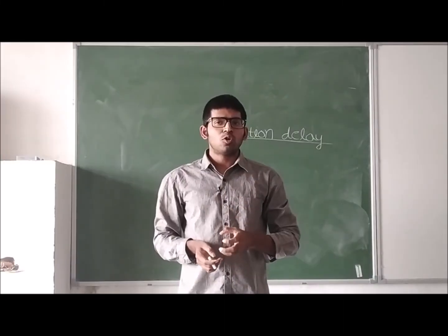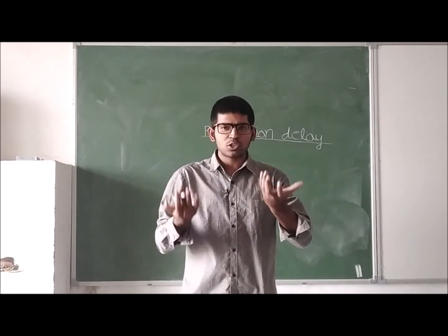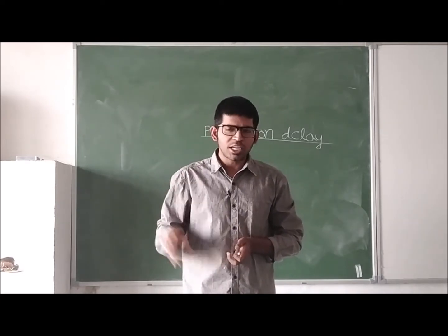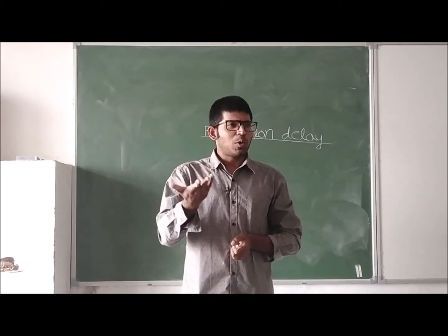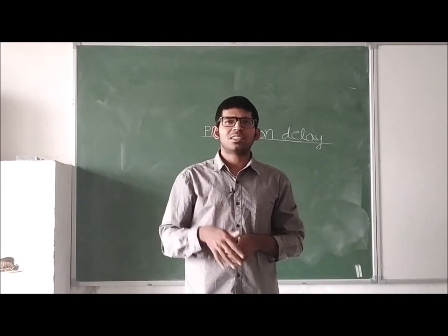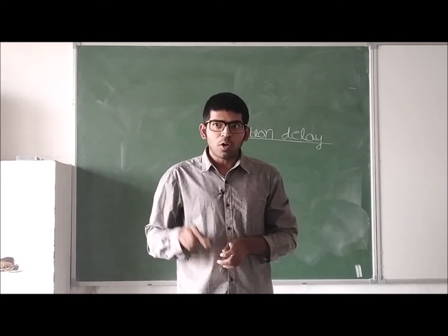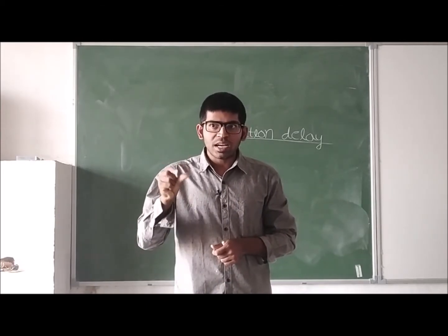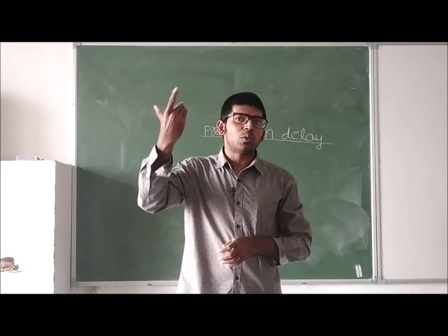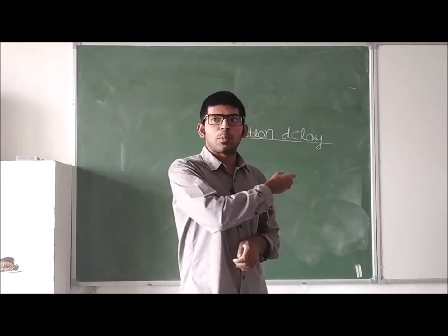Now we are discussing propagation delay. What is this propagation delay? Why do we use it? When we take a digital logic circuit, irrespective of whether it is unipolar or bipolar, saturated or non-saturated, whether it is diode transistor logic, transistor logic, or emitter coupled logic, ECL, we want to know the speed of this digital logic circuit, how fast it can give the output. That parameter can be known by using the propagation delay.